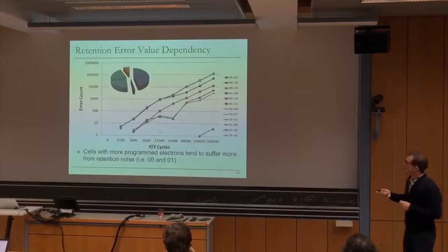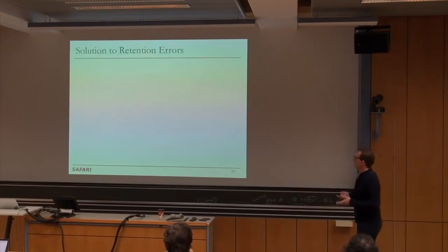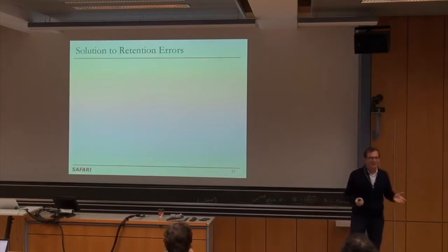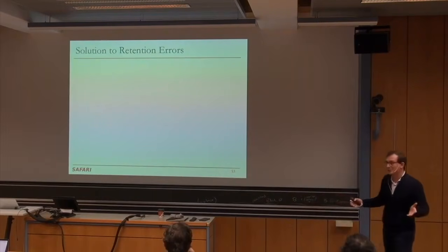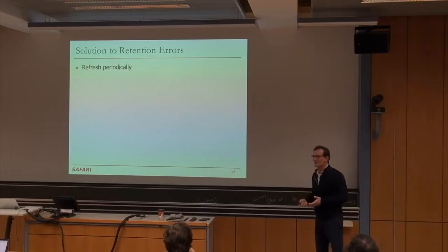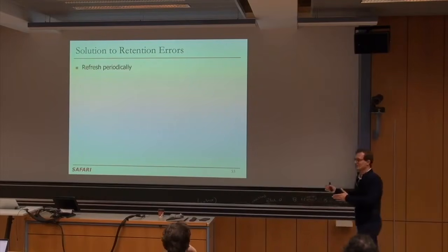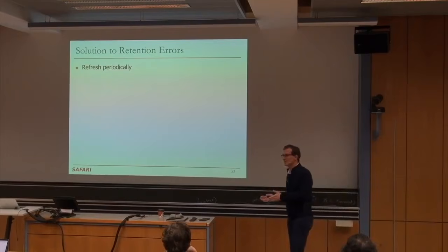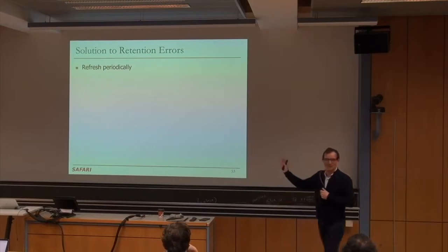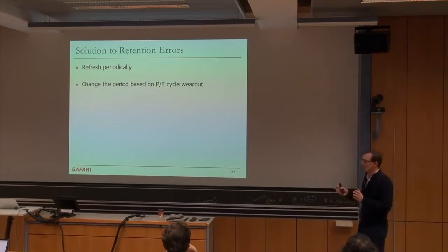Okay, we talked about this. Now we have retention errors. How do you cope with them? Well, you can add ECC, but we already know that that's not a good solution to retention errors, right? Well, we have another solution, which is refresh. And we're going to do that. This is non-volatile memory, flash, and many people don't know that it's actually refreshed, but now everything is refreshed in flash, especially in data center SSDs where things are powered on.